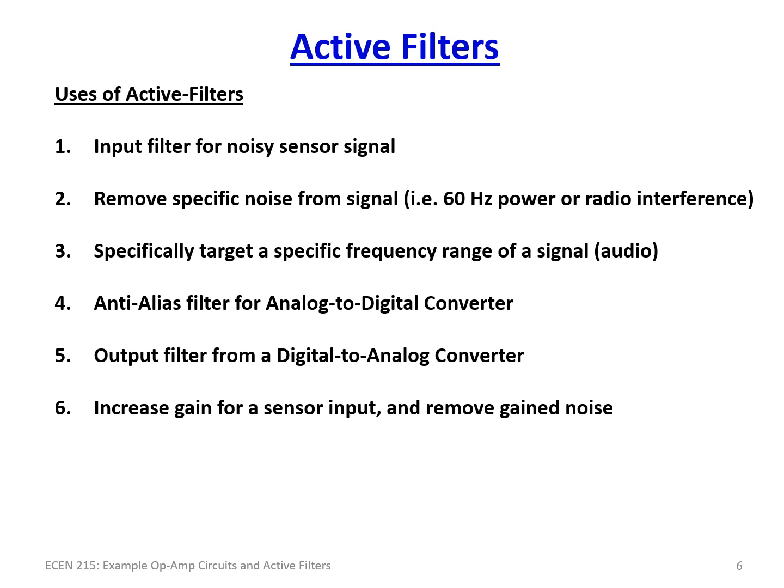But the noise that's being amplified is usually going to be in the hundreds of hertz, if not kilohertz range and above, and as such you're going to want to amplify, but yet at the same time put a low pass filter in there to reject that noise.